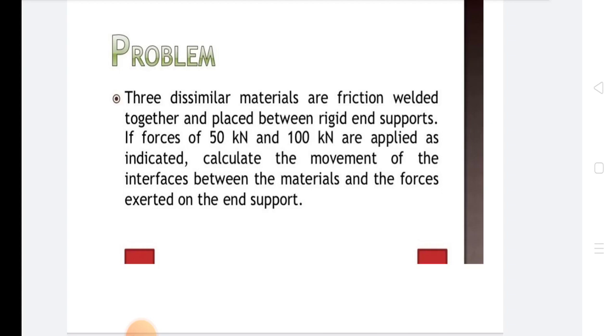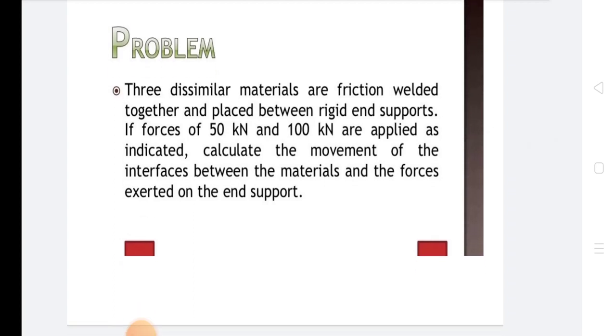After this, there is application of boundary conditions. Various boundary conditions are imposed prior to solution of the problem to obtain a non-singular solution. There are three methods of applying boundary conditions for an FEM problem: the elimination method, the penalty method and the multi-point constraint method. In step 6, to determine the unknown parameters, after imposing the boundary conditions on the global equilibrium equations, unknown parameters such as nodal displacement, element strains and stress can be obtained.